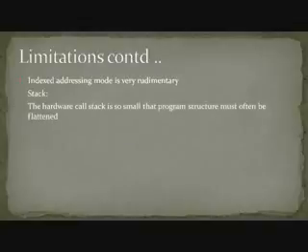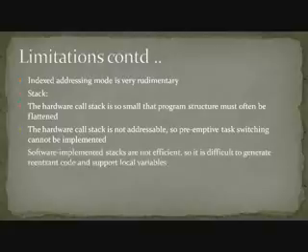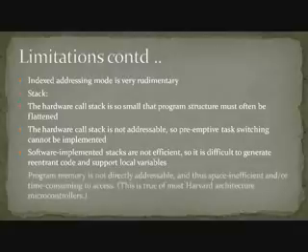Stack. The hardware call stack is so small that program structure must often be flattened. The hardware call stack is not addressable, so preemptive task switching cannot be implemented. Software-implemented stacks are not efficient, so it is difficult to generate reentrant code and support local variables. Program memory is not directly addressable and thus space inefficient and/or time consuming to access.